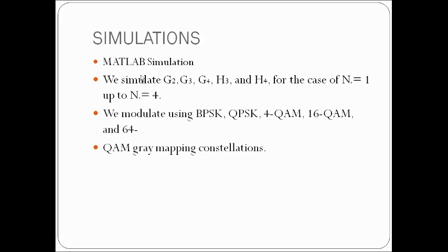The simulation framework is developed in MATLAB by leveraging the Rayleigh model as described in the introduction. We simulate G2, G3, G4, H3 and H4 for the case of n equal to 1 up to n equal to 4. We modulate using BPSK, QPSK, 4QAM, 16QAM and 64QAM gray mapping constellations.